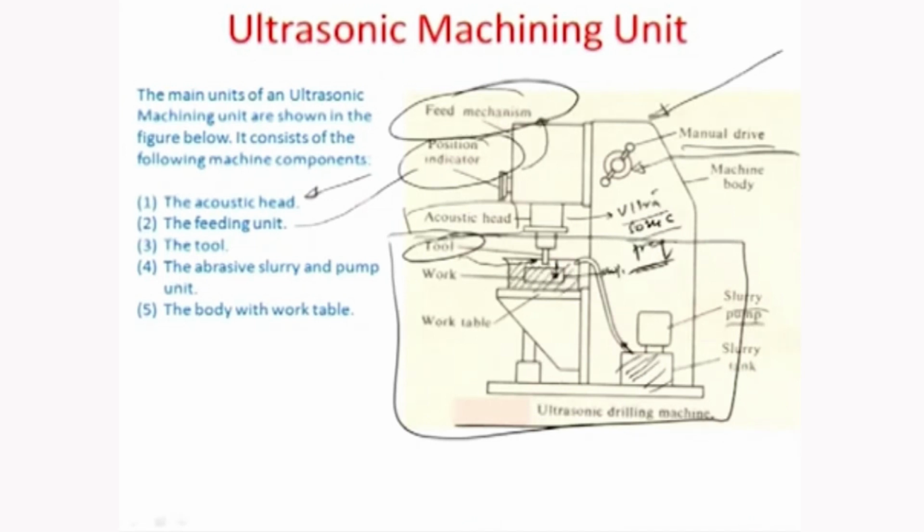So the work is actually immersed inside this cavity, which already comprises a flowing abrasive slurry, and so there is a continuous flow of the slurry into the work zone and taking away of the slurry, meaning that the debris which is generated is also carried away by the viscosity of the material, which has the abrasive particles in it.